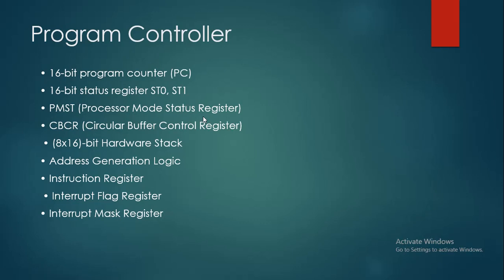The processor mode status register resides in the memory mapped register space of data memory page 0 and can be saved in the same way as any other data memory location. This PMST can be acted upon directly by the CALU and PLU in the DSPs.